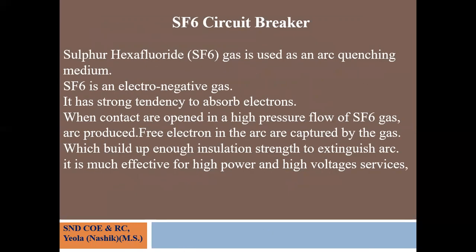The last circuit breaker is the SF6 circuit breaker. SF6 means sulfur hexafluoride gas. Sulfur hexafluoride gas is used in the SF6 circuit breaker as an arc quenching medium. SF6 is an electronegative gas. It has a strong tendency to absorb electrons.